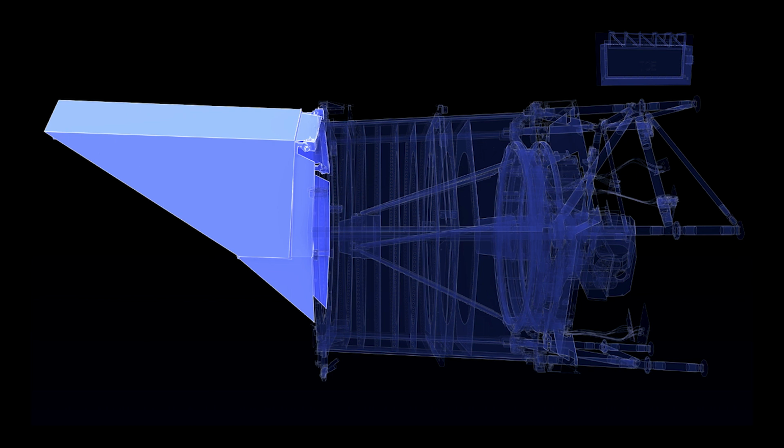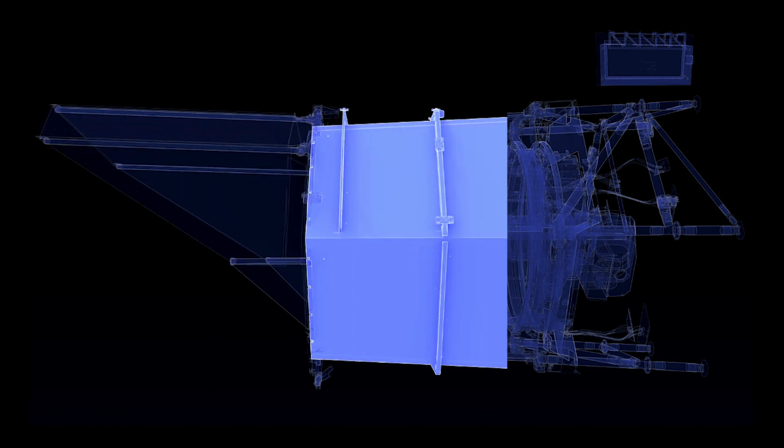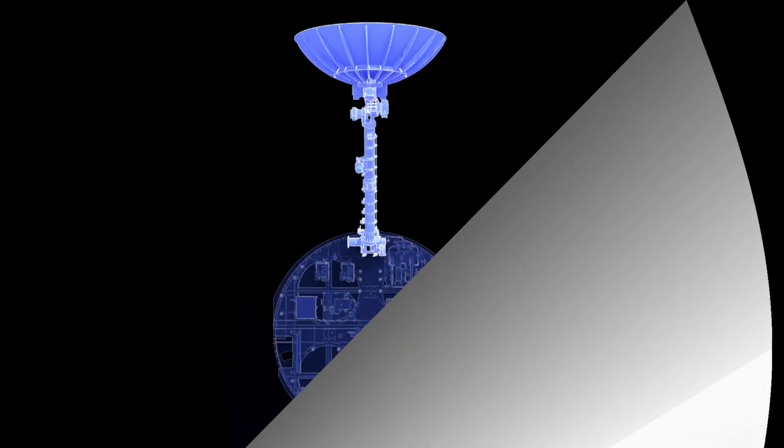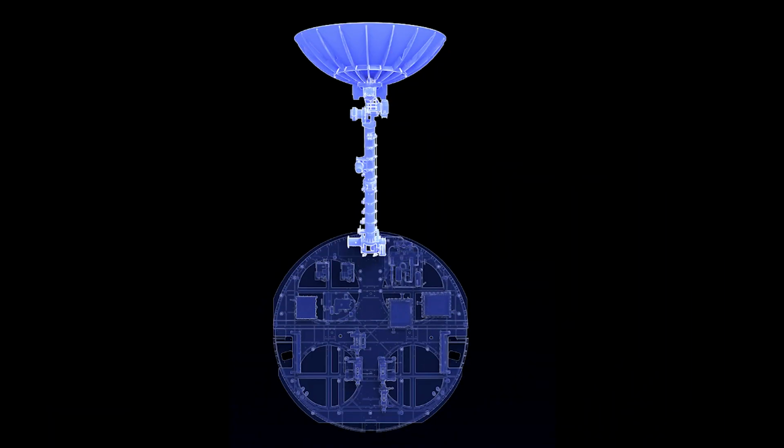This sunshade is deployed once in orbit using a soft material attached to support booms and remains in this position throughout the observatory's lifetime. The outer barrel assembly, OBA, will protect the telescope from stray light and help keep the mirrors cool. It also serves as the structural support for the solar array sunshield and deployable aperture cover. The OBA is connected directly to the upper deck of the spacecraft support system's primary structure with a series of struts that extend past the WFI and the coronagraphs. The communication module has 2 main instruments.